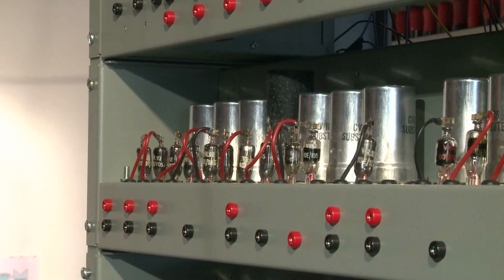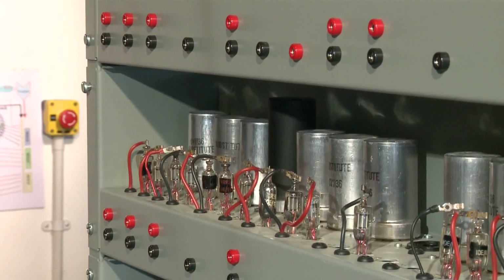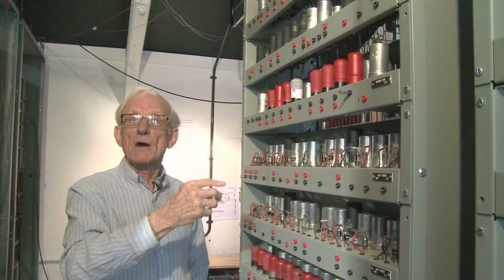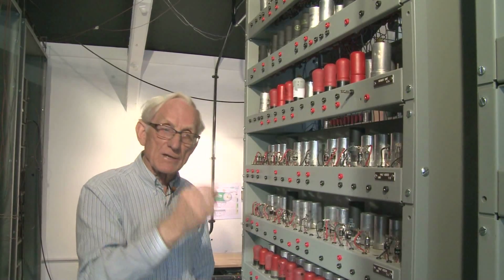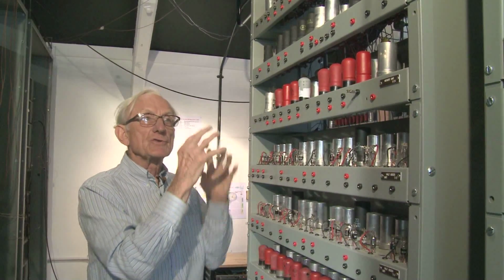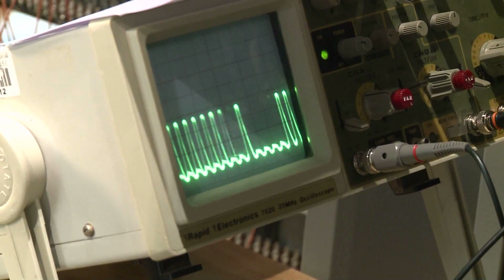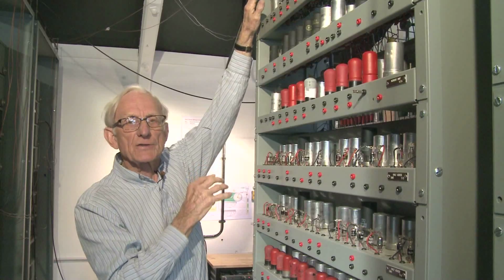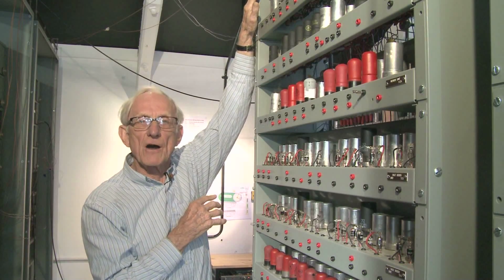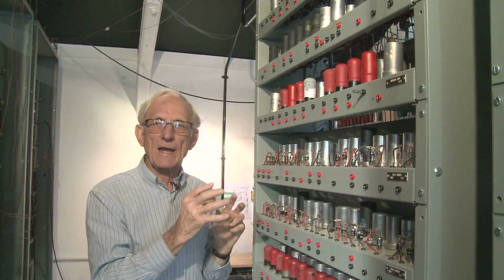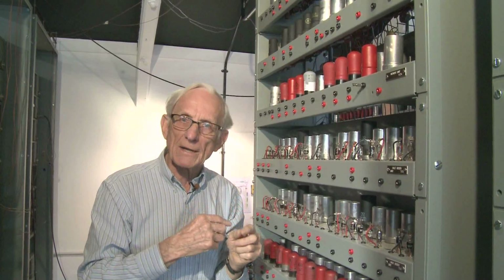And consequently, the number in the tank, 18 bits long, is counting up like fury every 36 microseconds, and very rapidly gets to 250,000 and then starts at naught again. And we can see that counting up going on the oscilloscope. We are only interested in the least significant 5 bits of that count, because those 5 bits are counting from 0 to 31 and back to 0 and 31.